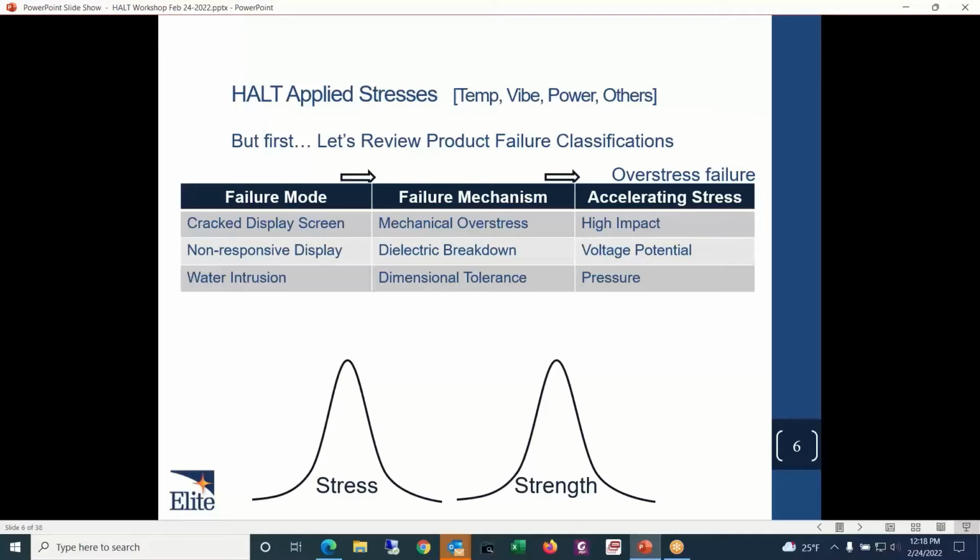And again, a way to evaluate that going forward might be to apply more water pressure, submerge the device in more of a water bath, or put more head pressure above the water bath to produce more pressure and try to press water into the device.